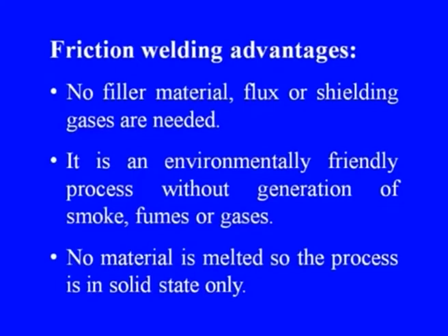Then no flux or shielding gases are needed, they are not used. So, that brings down the cost of the process also to some extent, because shielding gases are sometimes costly, and moreover they have some environmental implications as well.